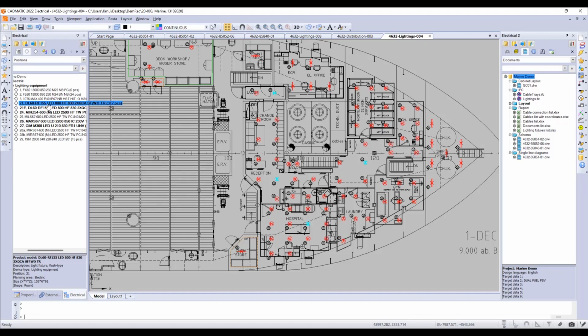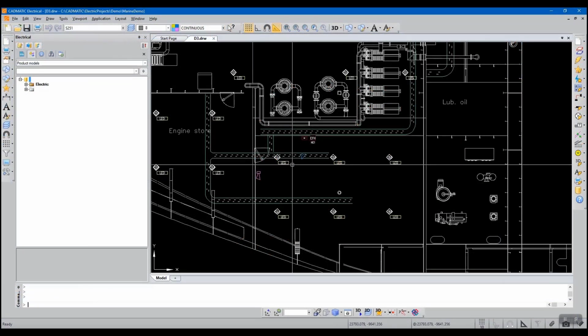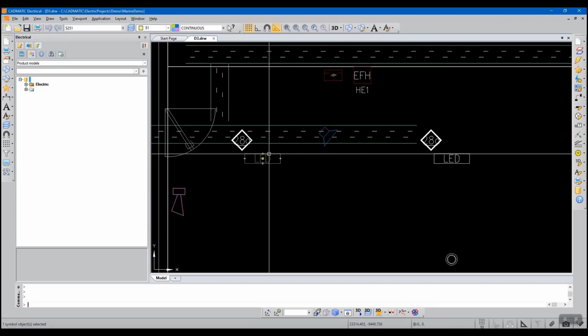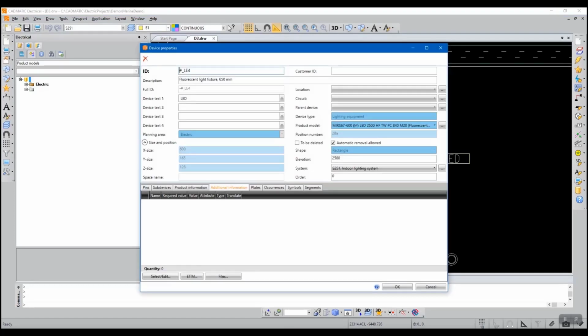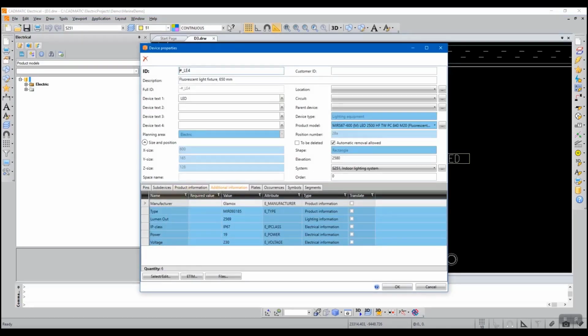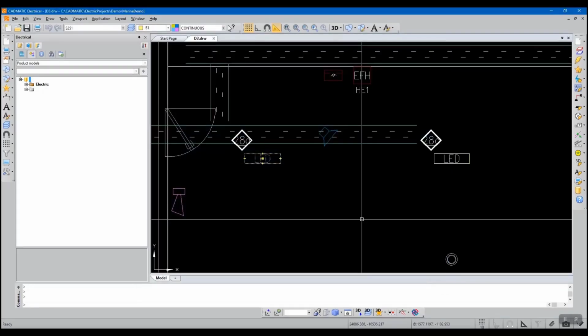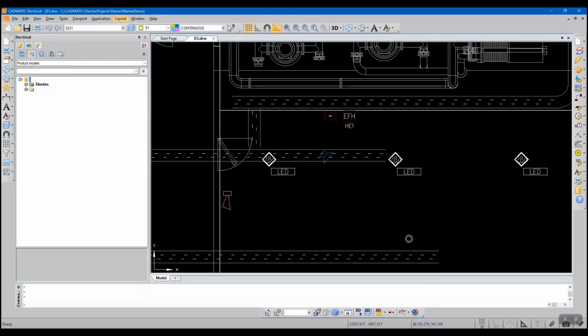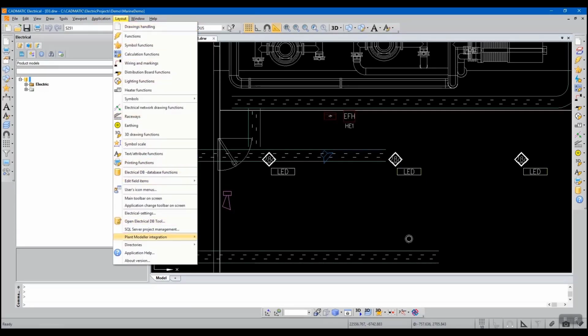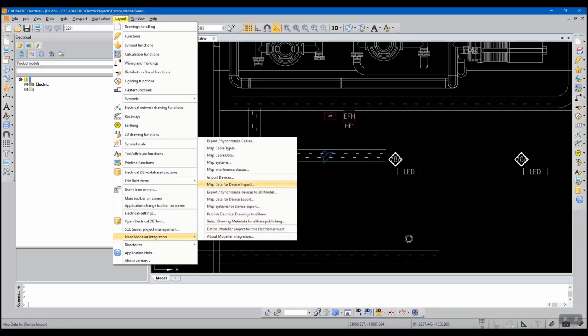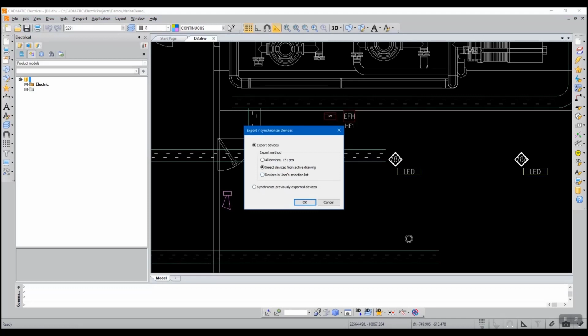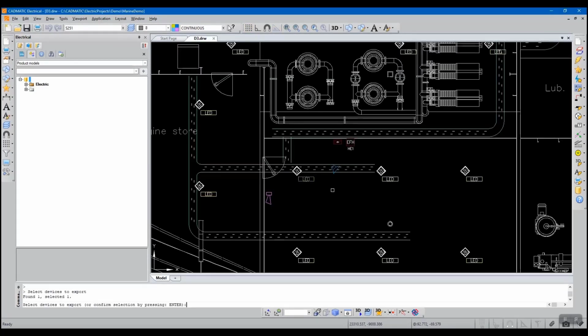After the electrical designer has placed the luminaires, the mechanical designer can use this information to insert or multi-insert electrical objects in 3D model. I use this video to explain how this integration works. So first we have here in electrical, we have luminaires, product models that has all the information about the manufacturer, about the 3D model. Then the electrical is connected with the 3D modeling tool, and the electrical engineer chooses which objects can be now sent to the 3D model.